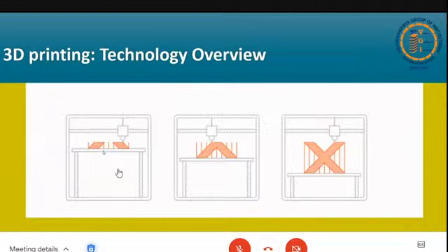You can see these layer marks that you are seeing on the X, the horizontal layer marks. These layer marks will be thicker if you have a thicker layer height, and the part will print faster. But if it is a thinner layer, you will not be able to differentiate between two lines, as they will be very close, but it will take a very high amount of time to print.